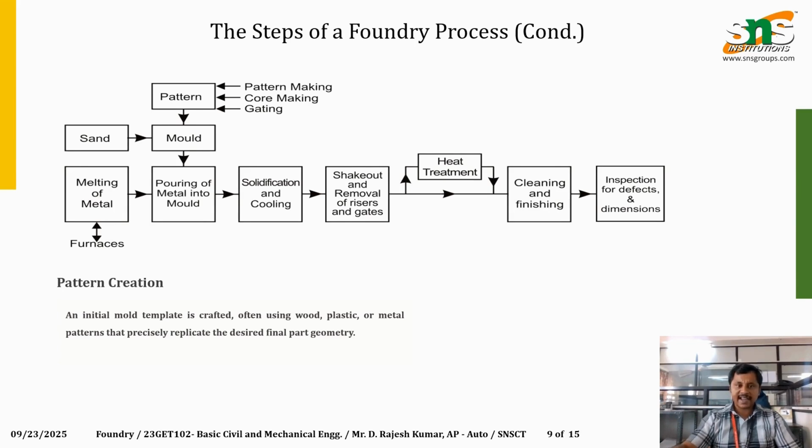So pattern, then sand preparation, then melting is done, then pouring, then it is allowed to solidify and cool and then it is removed. The final casting is removed. If required, heat treatment is done, then cleaning and finishing, then finally inspection. So these are the broad steps that are carried out.